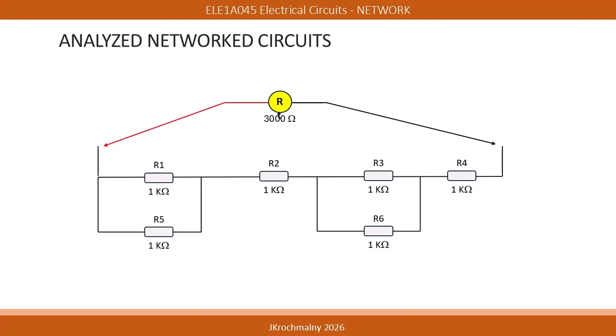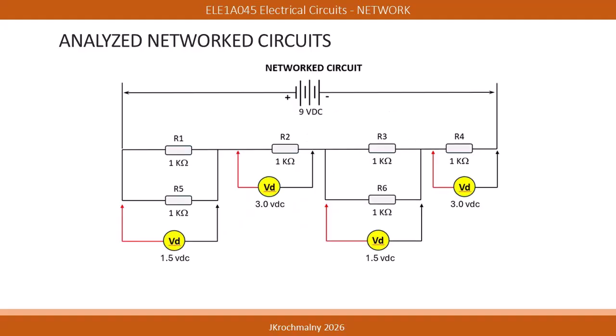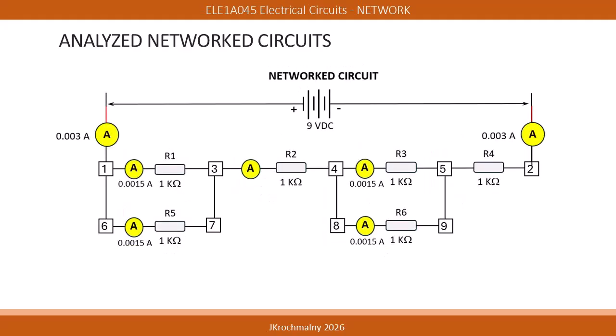In summary, networked circuits can be simplified and analyzed using our previous knowledge of Ohm's law applied to series and parallel circuits. We can also verify our calculations by utilizing multimeters in different configurations of voltage, amperage, and resistance.